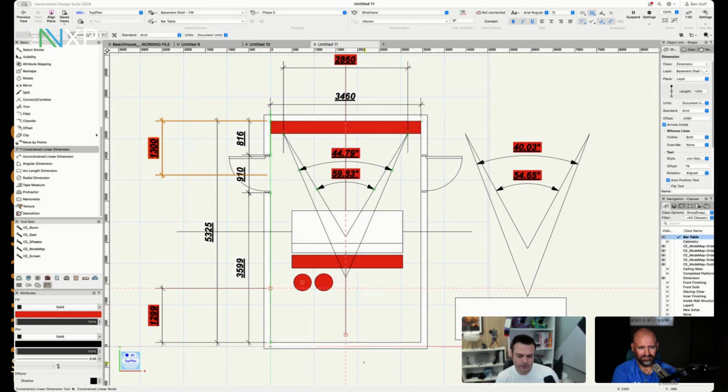So, you might say if you're going to have subs all the way on the back wall, using a traditional 4 on the floor subwoofer layout might give you more options to help the back row. This is a danger that a lot of enthusiasts find themselves in: that auto EQ is a get out of jail free card, and it's not. It can actually make things significantly worse.